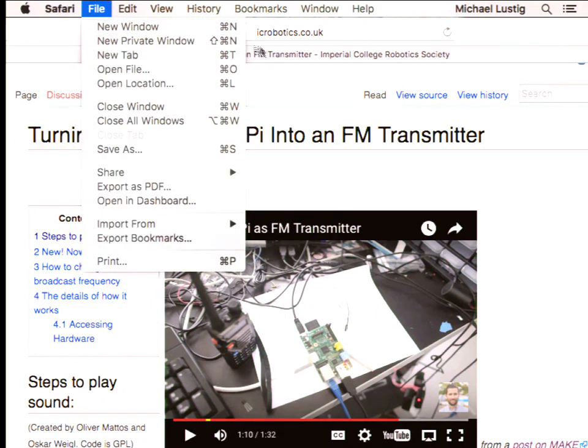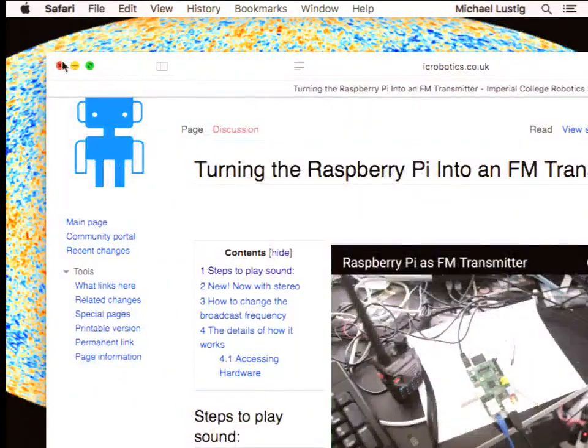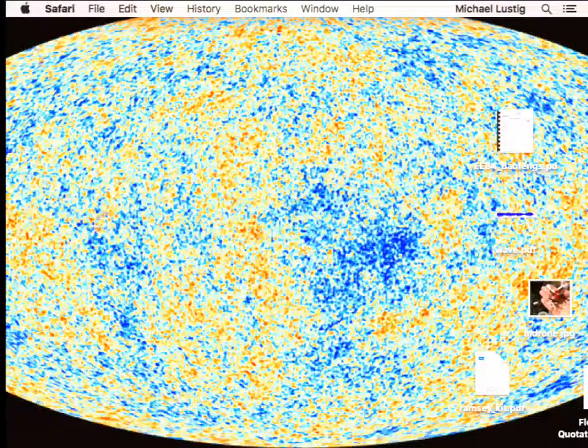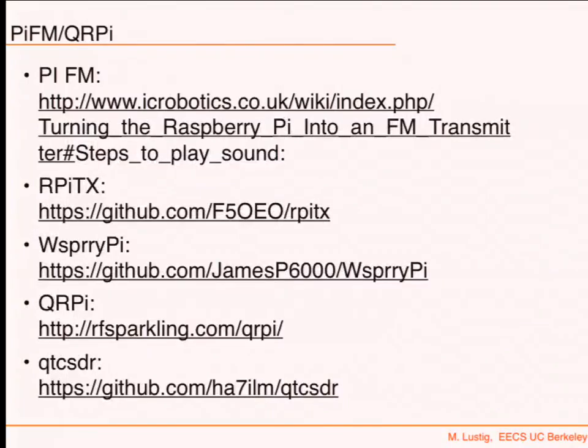That's pretty awesome, right? So anybody that has one of these can just go home today and do it. It's really easy to do. And basically use this to create some frequency modulated signals. Then, people thought about it a little bit more, realized that with pin 18 you can also change the amplitude by about 8 levels. So, hey, maybe you can do AM modulation, maybe even single sideband and so on and so forth. This is the project RPI-TX.